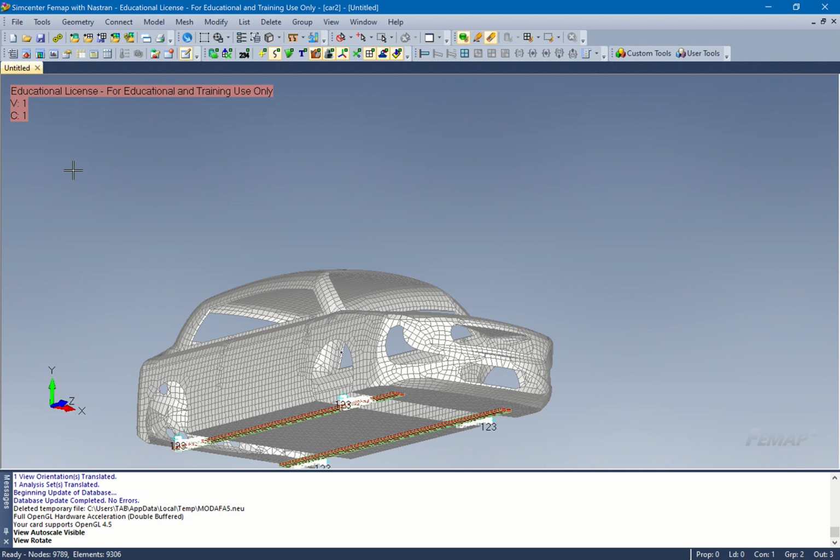Also, I can search the pictures on there. So I did that. I did the Bay Bridge test. No, there's the King's Bridge. Really amazing. They called me up and said, we test the bridge. Some of the things was short here. But the bottom line is we want to excite the bridge. The bridge is about 3 times the size of Prince Thomas Bridge. So I made up some ramps, 6 inches high, and then we loaded up 2 trucks with maximum capacity of about 105,000 pounds.